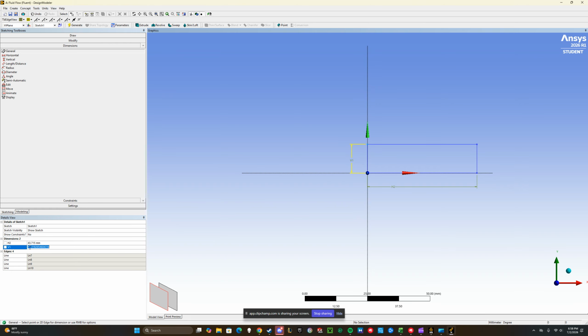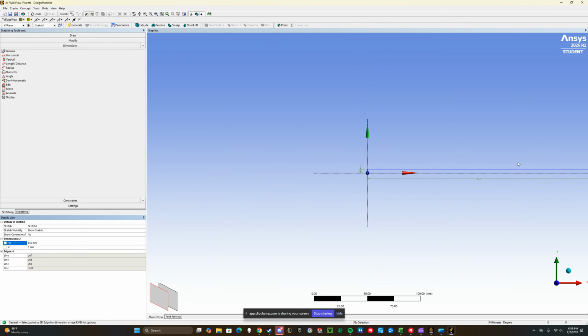So I chose 3 millimeters height and 450 millimeter length. I got this from previous examples in this class, so it should be working fine. The Reynolds number calculated was far below the required Reynolds critical.